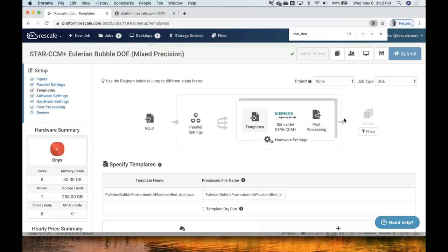And so that really gets you to the point where a lot of us that went into engineering and simulation, what got us intrigued is asking these what if and why questions. What if we have constraints of this nature around the blade pitch? Maybe it's from 35 to 55 degrees, but we can also change materials, etc. And increasing that parameter list that we want to change, instead of doing a parametric sweep, do an intelligent look at the design space, an exploration of the design space.